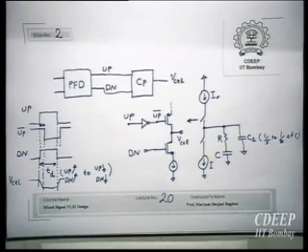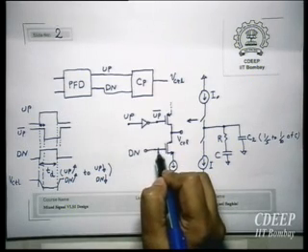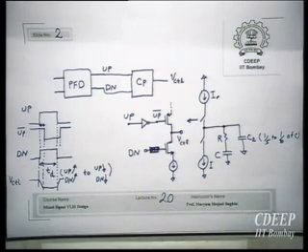The second choice is better, because if I go with two inverters, then effectively I have to increase the delay of one inverter. Then effectively I am creating a delay between up and upper. So it's better to go with just a dummy switch here. It can be just a dummy transmission gate which is always on.